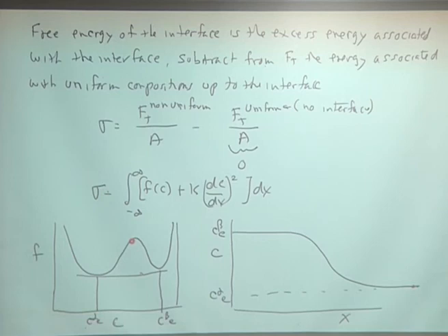So is that composition stable or unstable? Is this thing stable or unstable? And the answer is it's stable because you have this gradient energy coefficient, and we'll show that in a second. So the gradient energy coefficient allows these compositions in here to access the spinodal, which is where they're unstable.